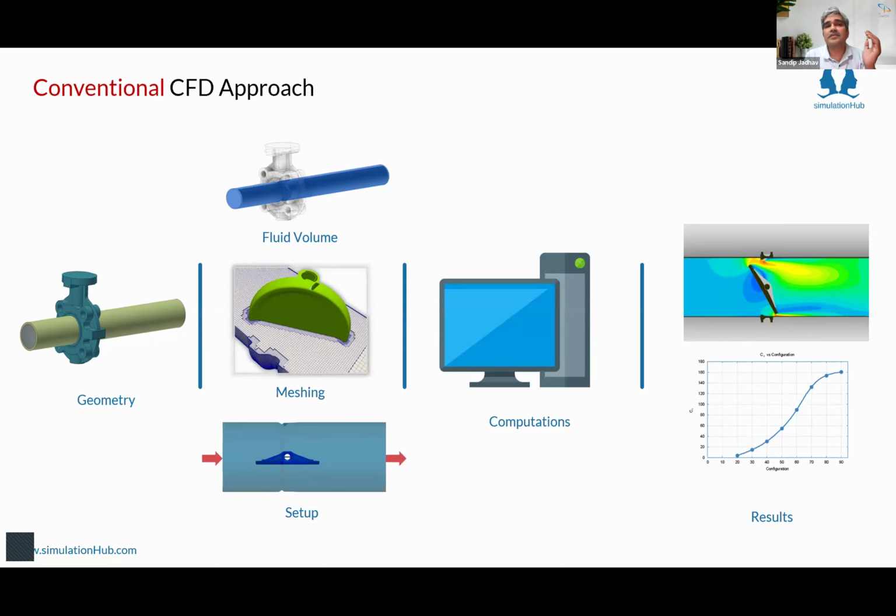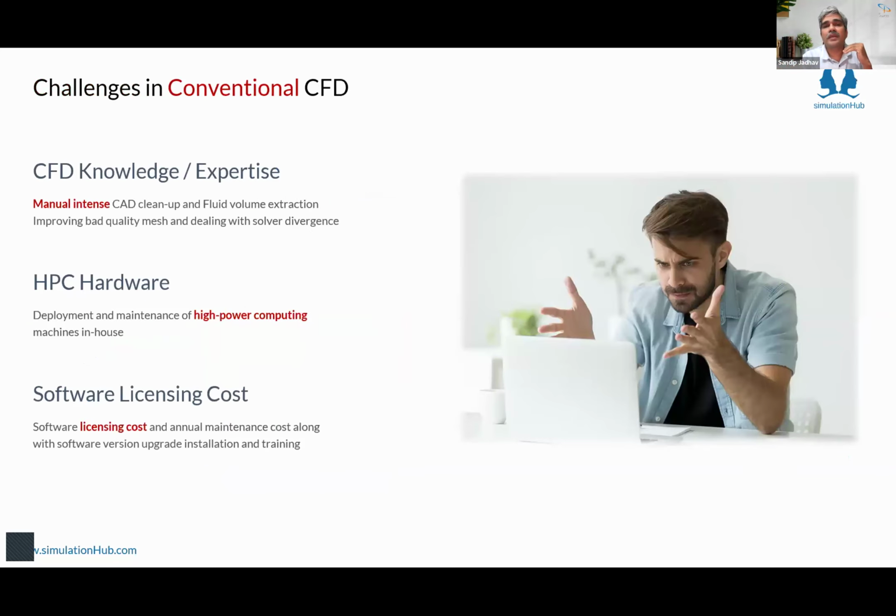And that means, if you go to the next slide, Praveen, we have seen many of the CFD users do not have this detailed level of understanding. If you go to a smaller valve size, 2 inch, half inch, again the whole thing changes. It is not the same boundary conditions as what you do for a 6-inch or 8-inch valve. If you go to higher sizes, 36-inch, 48-inch, again things change. You need to come up with a different scheme, different turbulence model, and different setup.